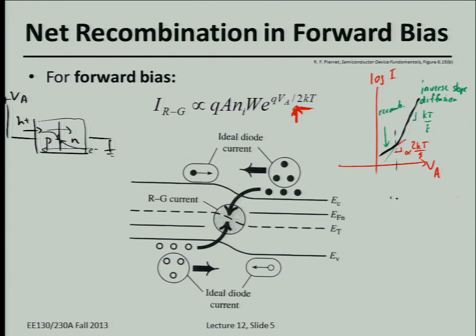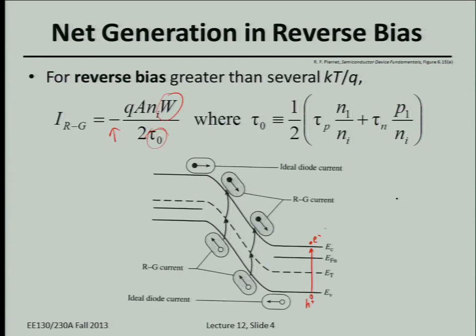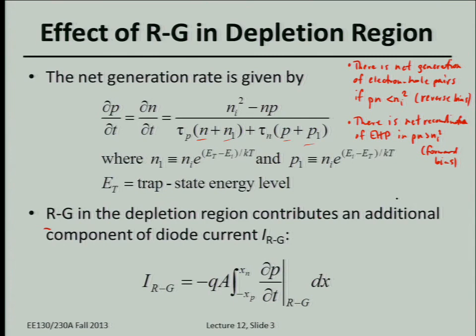Okay, so there's a key requirement for recombination to occur. So what is that? Traps, yeah. So there are these allowed energy states within the band gap, right? And so that's kind of hinted at here in this equation, right? Depending on the energy level of the traps, they can be more efficient for recombination or not.